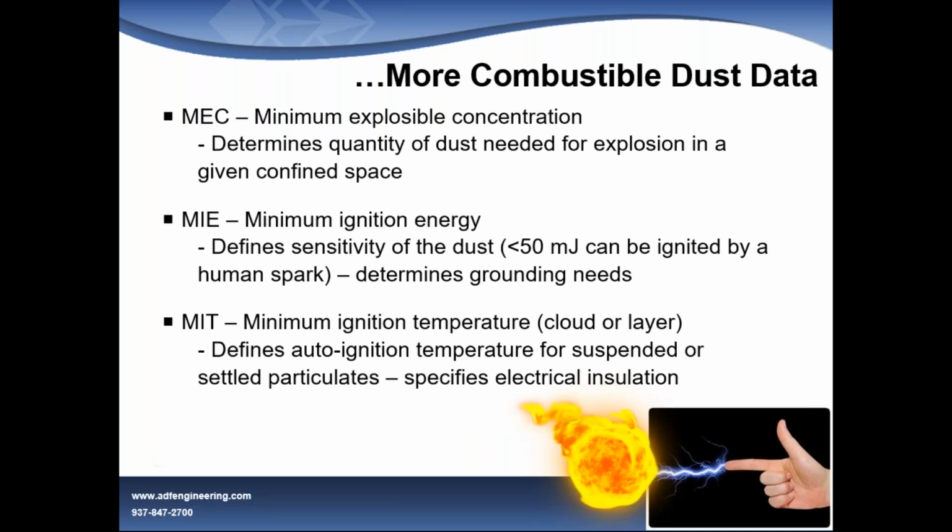Other three tests that I personally recommend, one is minimum explosible concentration. That's like looking at the LEL of a flammable vapor. It is an option for you to try to run or operate your process below the minimum explosible concentration. If you can keep the quantity of dust in the equipment below that minimum explosible concentration, you don't have to worry. If you only get a cup full of dust once a month and it's never going to hit the explosible concentration, you're done. You don't need to worry about it.